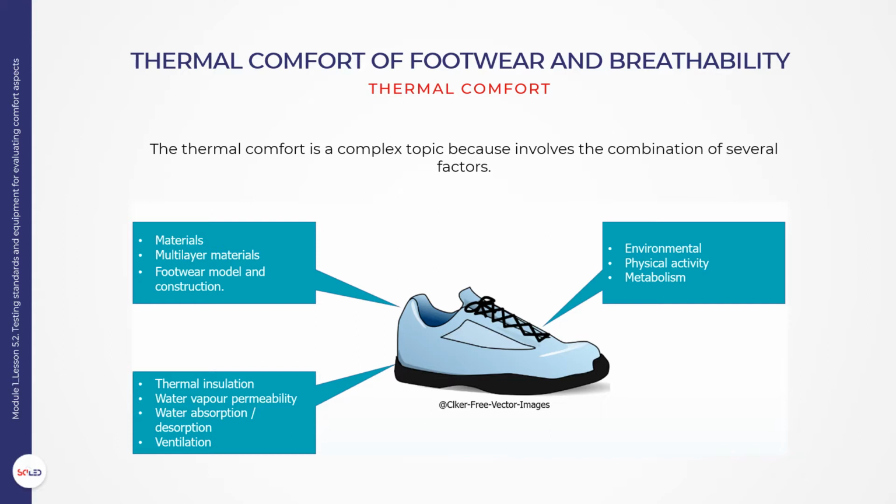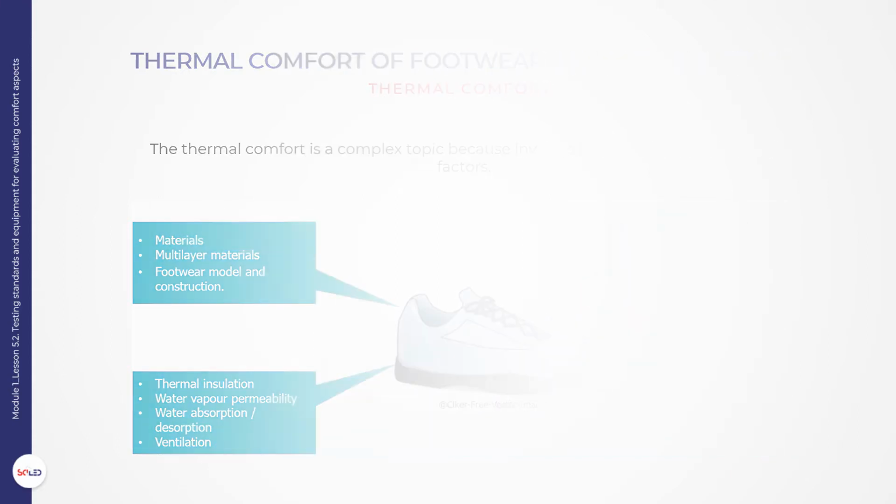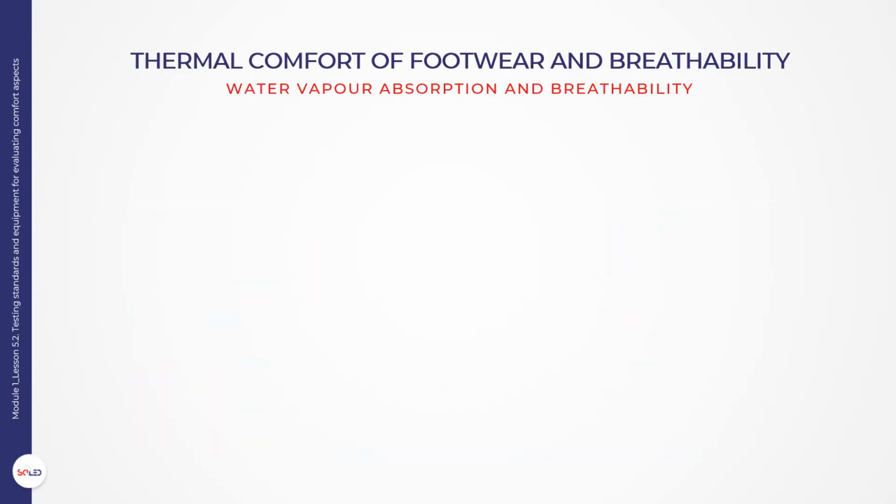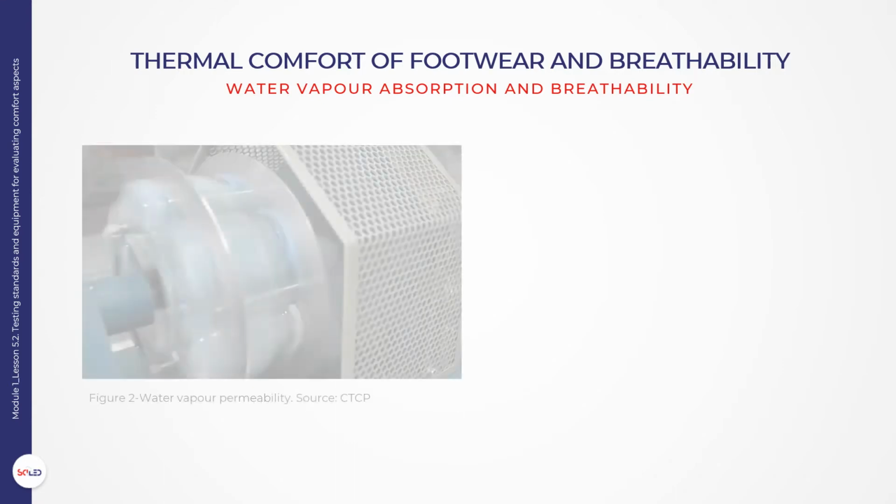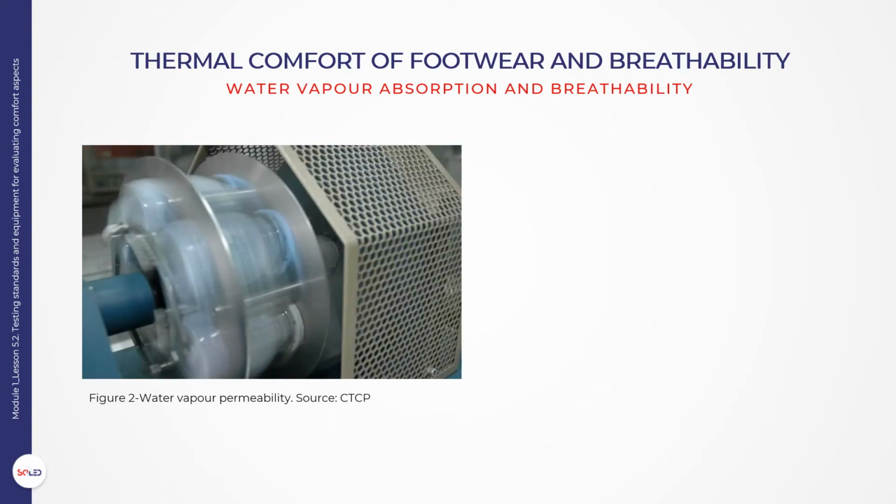Regarding materials, it is important to evaluate the water vapor permeability and absorption, water absorption and desorption, and thermal conductivity. Water vapor permeability and water vapor absorption. The standards ISO 20344-6.6 and ISO 17699 describe methods to evaluate the water vapor permeability of lining and upper materials.